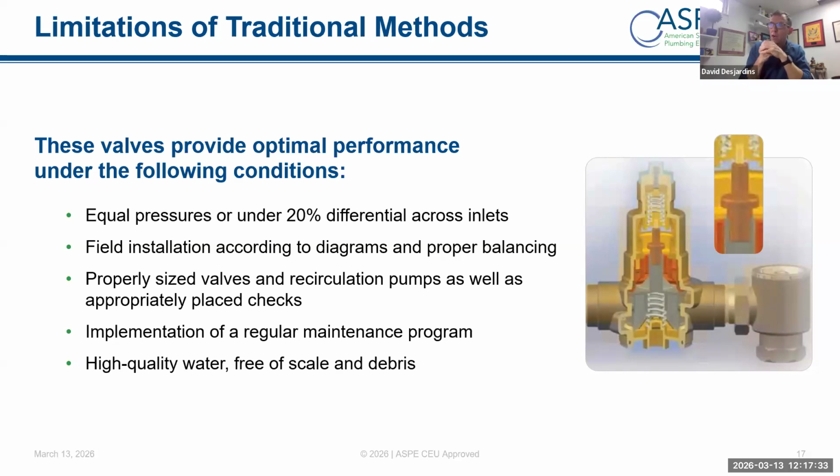On sizing, you don't want to size them per line size. That's another thing I see. If you oversize the valve, that element will cycle a lot, and then you'll end up having to rebuild it quite frequently. A lot of manufacturers have tools on their websites where you can size this, and you'll notice that it will size it for your design flow rates. Then you have your minimum flow rates as well, and typically I look at recirc flows.